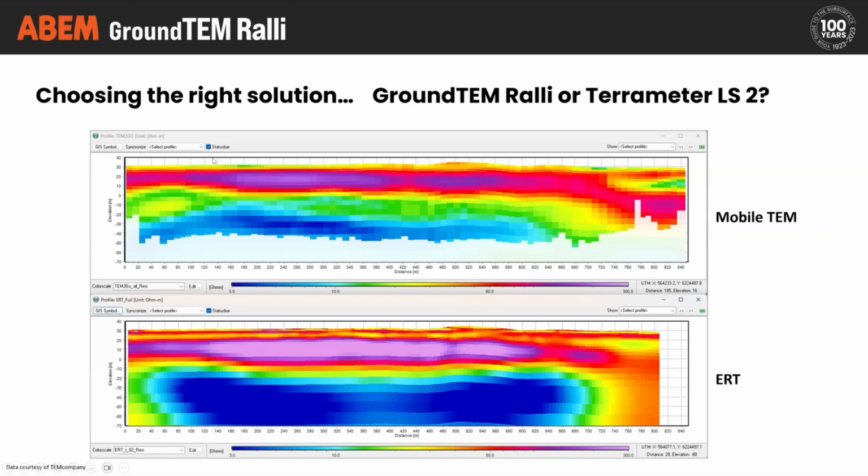Again, with the near surface, we see that the ERT is delivering a little bit more information, as expected, because we have that slightly better near-surface resolution. Now, this plot is a little bit unfair because the ERT data hasn't been blinded. By blinded, I mean cut off at the point where we think the model is becoming unreliable, whereas the TEM data has been. So you would probably find that the DOI on this would be somewhere through here, and more comparable to what's on the TEM system.